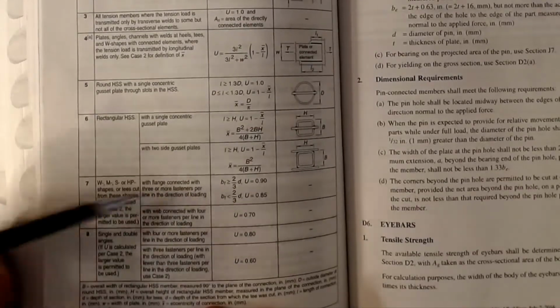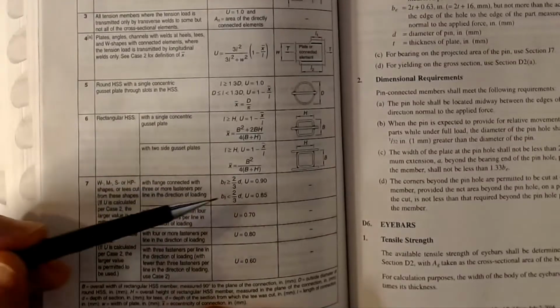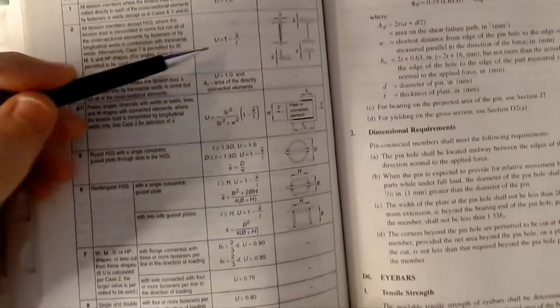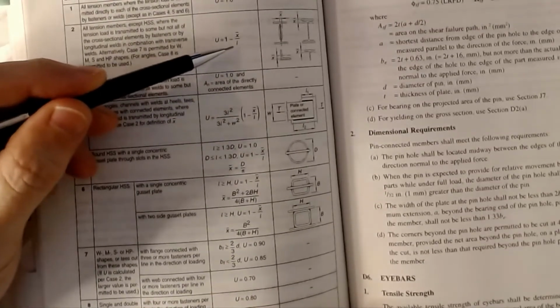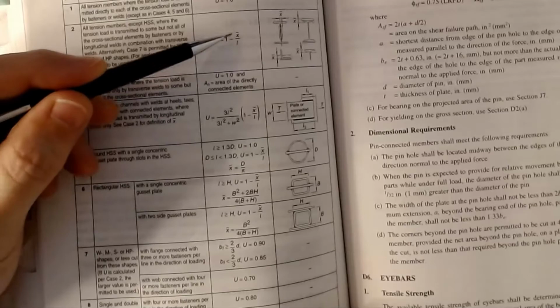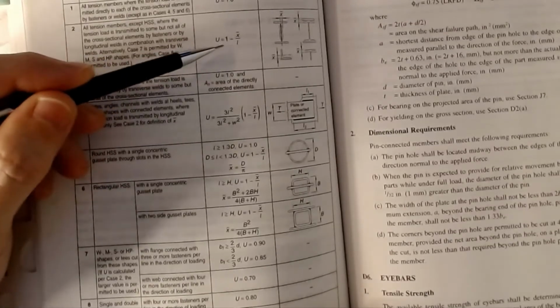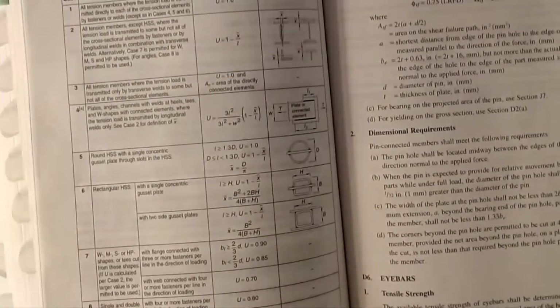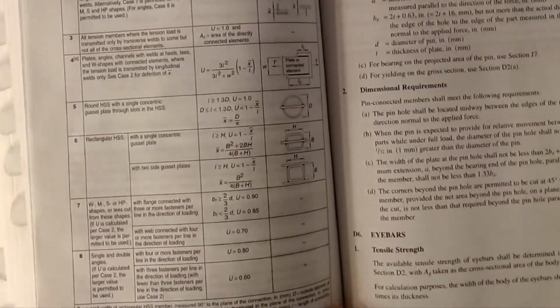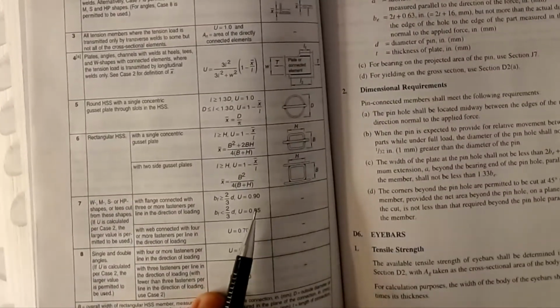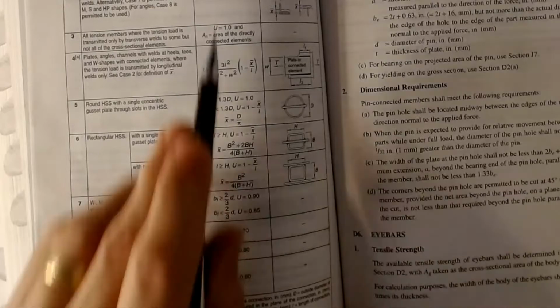Now these are really easy to use, but they may be a little conservative. If we go back and look at case 2, if the length goes up, then the second quantity goes down. I can actually get close to 1 if I have a really long connection in the flanges. So these are good first-estimate guesses, and if I want to sharpen my pencil a little bit, sometimes I can get a savings in case 2.